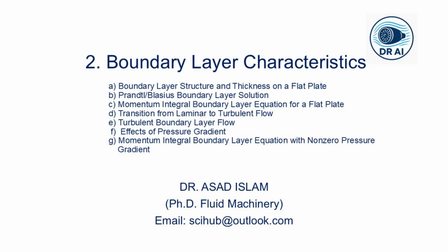So for today, what we have discussed up till now is that the drag and the lift come from both pressure and shear stress distributions. The Reynolds number fundamentally determines the flow character, and at high Reynolds number, the flow divides into boundary layer and inviscid regions. We also saw that the boundary layer separation creates pressure drag and explains D'Alembert's paradox.